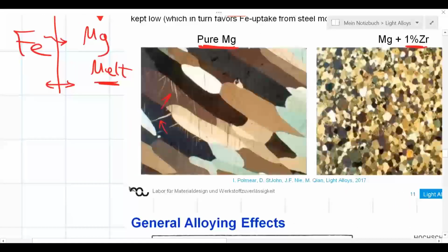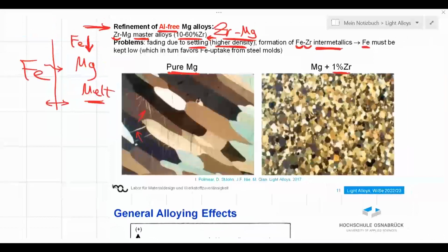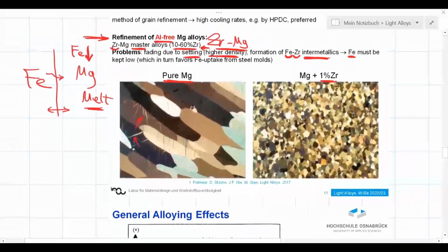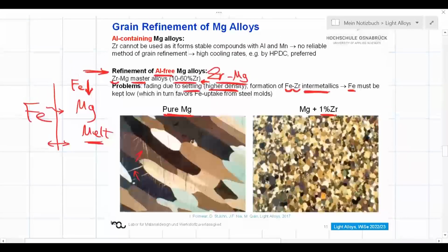Right? It is hard to deal with magnesium alloys. If you would like to prepare a specimen for metallography, you have to be very careful. It is very soft. You readily get scratches. It gets deformed at the surface. And if you're deforming that, you can probably also activate some of those slip systems and also some of those twinning systems. Right? Deformation is not only by slip, but there are also some twinning systems which could activate due to plastic deformation. And in this case, plastic deformation is coming from specimen preparation, which makes handling of magnesium